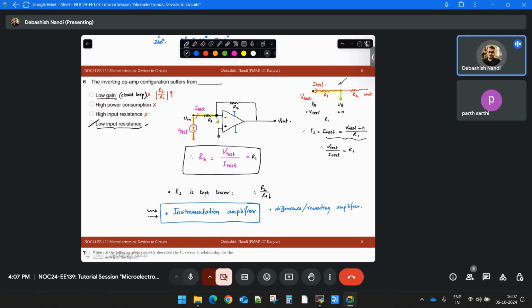It is a similar circuit connected in a coupled manner. The way we have gone from your single-ended op-amp to the double-sided differential pair, the same philosophy is applied here also. Two inverting amplifiers are connected back to back. A common resistance is there in between, and those outputs are fed to another op-amp. So you just search instrumentation amplifier and you will get to know that. That is actually used in industry also in many control systems.